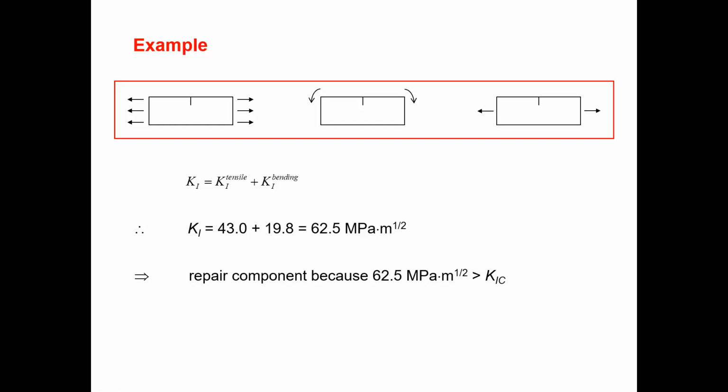For the repair part, you can fill the crack if you want, or you can machine it sometimes. So you can remove the crack, reduce the diameter, something like that. Or you can replace the bar sometimes.